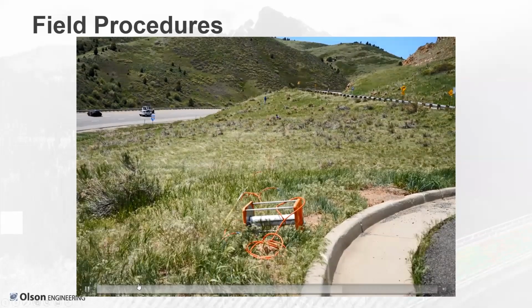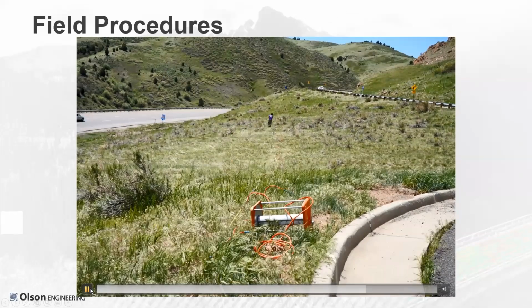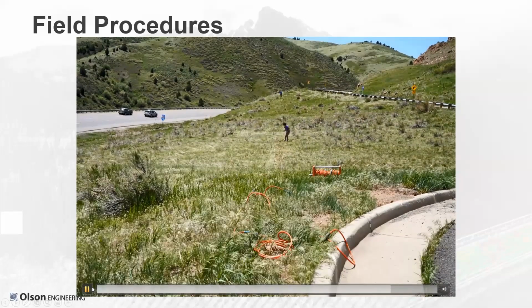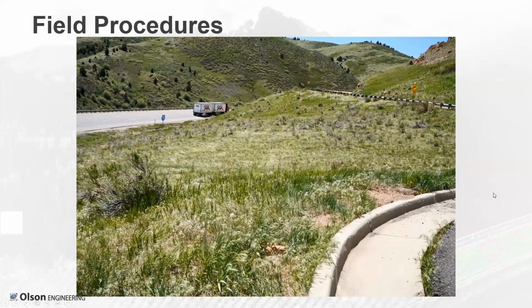continuing to hit the ground. And every location that he hits the ground, we refer to that as a shot point or a shot location. And you can see we're collecting. We are picking up our equipment, and we do this in the reverse procedure that we lay it down: pick up the geophones, roll up the cable, pick up the survey tape.